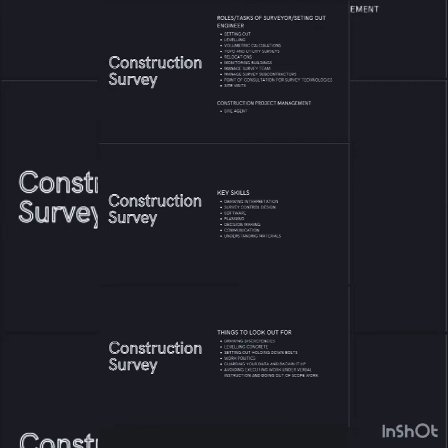Let's say for example, in terms of levels, there are other processes that happen that might affect your levels. Because material on site, from the material used to make a road to the concrete that's used on columns and floors, behaves differently when other tasks are performed on it. Let's say you level to the proper level, and then compaction comes through after that. It might lower your levels by millimeters that send you out of spec.